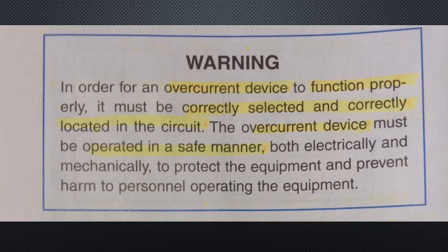Overcurrent devices are placed in a system so that only the section of the system where the overcurrent exists will be opened. Other circuits originating from the same power panel do not suffer a power loss from a remote fault.